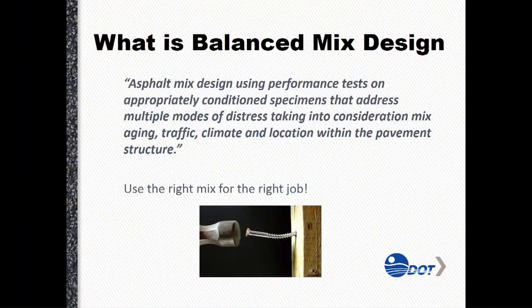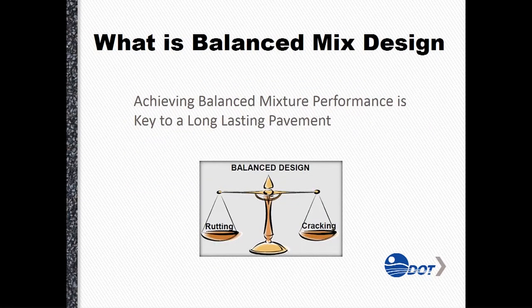So fast forward to the past couple of 3 or 4 years, we've developed a balanced mix design. And what is it? Asphalt mix design using performance tests on appropriately conditioned specimens that address multiple modes of distress, taking into consideration mix, aging, traffic, climate, and location within the pavement structure. Wow, that's a mouthful. We've got to use the right mix for the right job, right? Low volume, high volume, we want to really take a look at it.